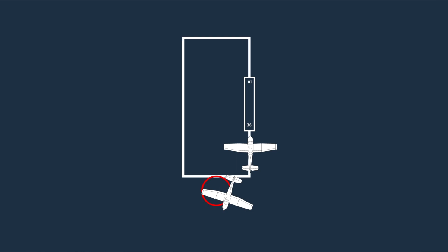And you have to coordinate this with other pilots on the frequency if you're flying into an uncontrolled airport. But also at a controlled airport, the air traffic controller might actually instruct you to do an orbit. Okay, so make sure that you're aware of this. So that's a bit of an overview of the VFR circuit.